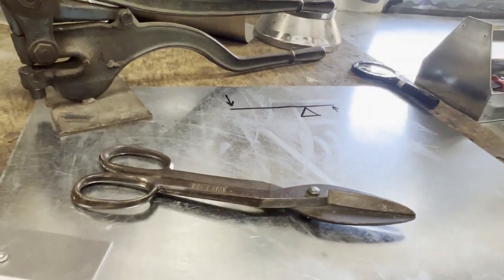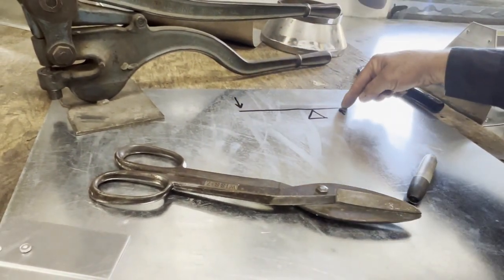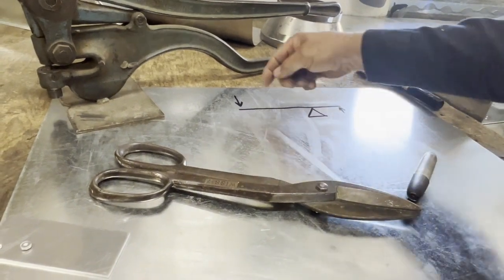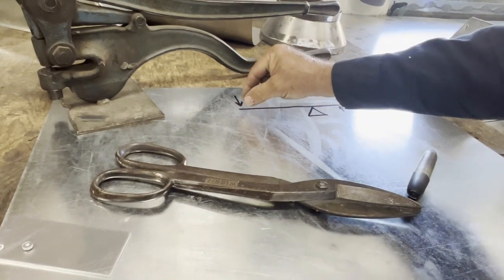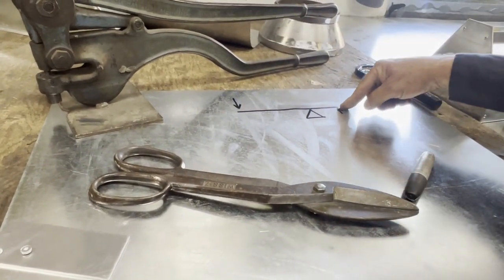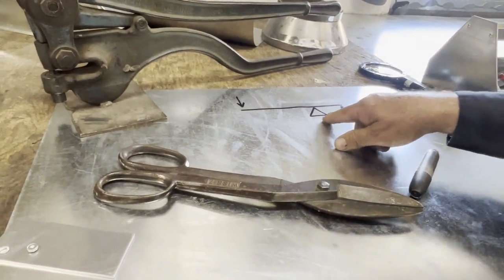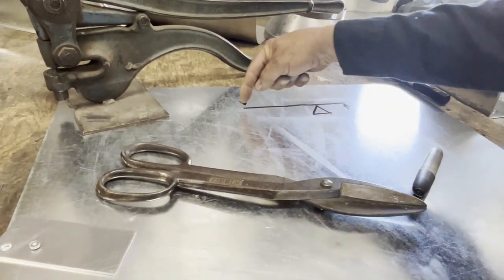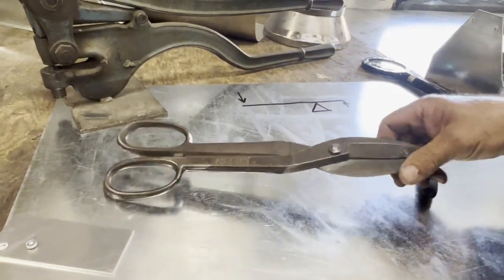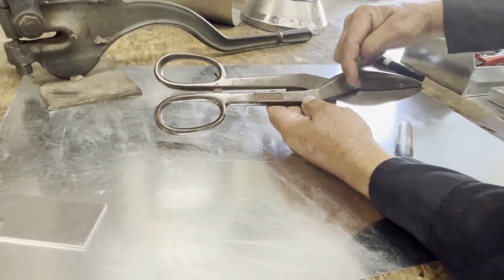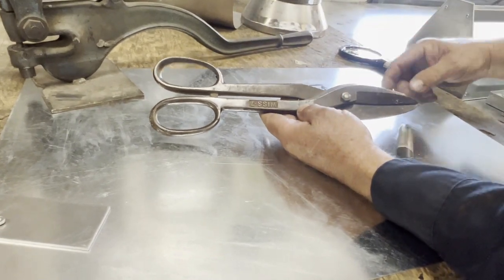So the trade-off is we need a lot more movement on this end to accomplish the same amount of movement on that side. But that is where the leverage comes in. So we have a lot of movement and we have a smaller amount of reaction or action. And we've done that just by moving the fulcrum, which gave us a longer lever, which gave us more leverage to perform the shearing action. That right there, that's what's happening. Here's our fulcrum. Our handle is longer than the blades.